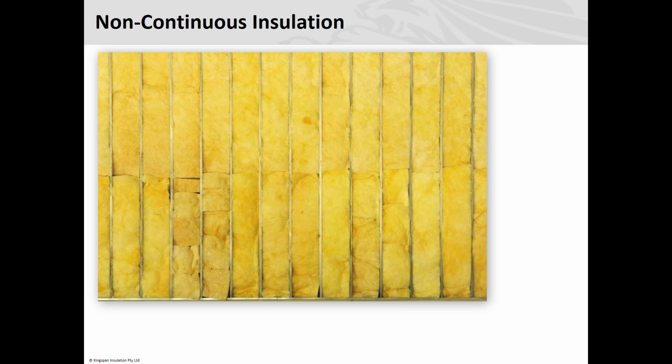Some of the problem with that is, on paper you've got a 6-star rating, but if the insulation is not installed correctly, or if the right glass the energy assessment said should go in didn't go in, it's not going to work effectively.